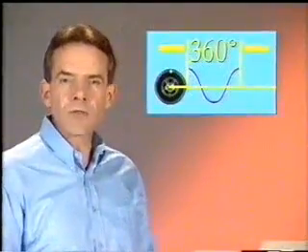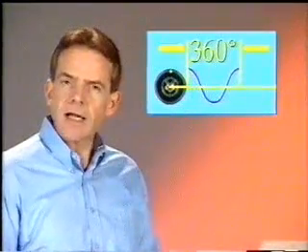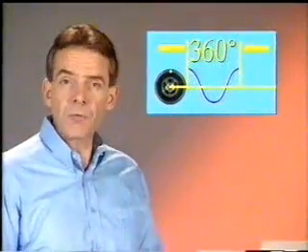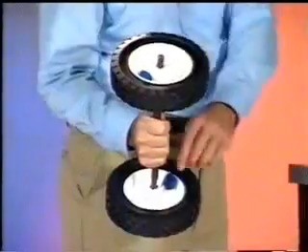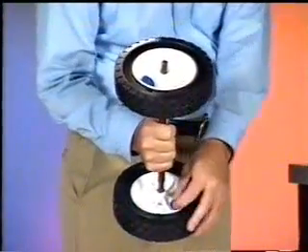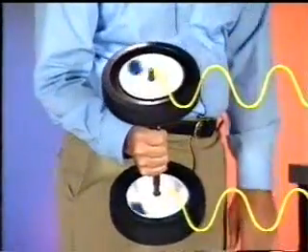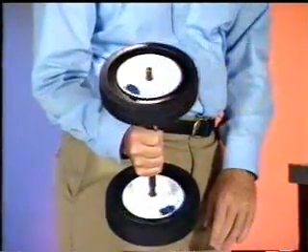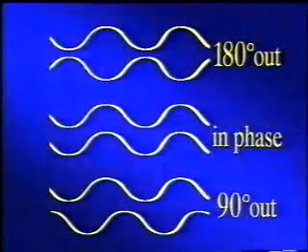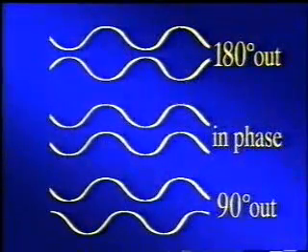It is important to understand that each revolution of the tire completes a full sine wave, and like the tire rotation, the corresponding sine wave is a full 360 degrees. When one weight is moved 90 degrees and the motion is traced, the sine waves will be out of phase by 90 degrees. With this example, we have been looking at the phase or relationship between the two unbalanced wheels.